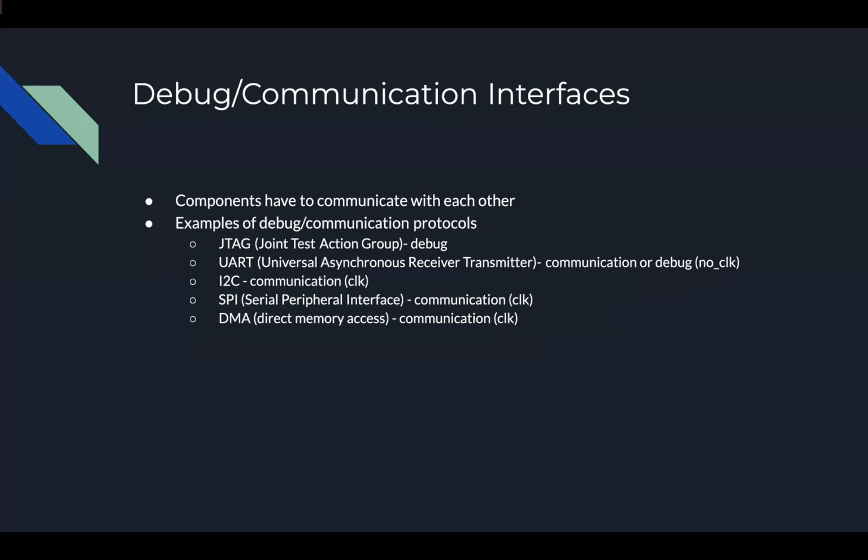The next one I want to talk about is UART, which is similar to the other communication protocols below, but is unique in that it is also used for debugging, and it doesn't require a clock to synchronize data. It just needs to either have some smart initialization code that synchronizes it, or it needs to start at the same time as the other device, and then continually send and receive bits at the same rate so that it never goes out of sync.